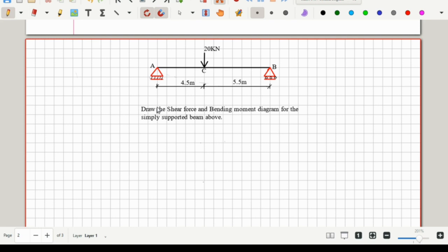And then on the right support, we have a roller support. Right. So let's begin. In order for this structure to be stable, we'd have to consider three equilibrium equations. So we'd have to consider the summation of all downward and then upward forces. So summation of vertical forces must be zero. Again, we'd have to consider summation of all horizontal forces.